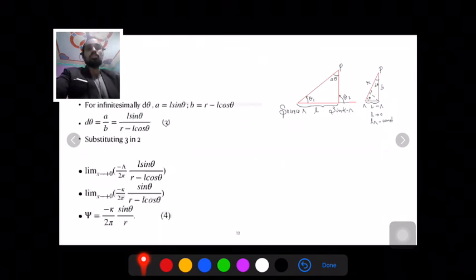This is the equation of a streamline in doublet flow, the equation of a circle, and this is the diameter. So what is my diameter? My diameter is k by 2 pi c. If I look at those two equations, R is equal to d sine theta, and R is equal to minus k by 2 pi c sine theta. So what is my diameter? My diameter is k by 2 pi c. This is the doublet family of circles that you see on your screen here. These are your family of circles, and all these different circles correspond to different values of the constant.